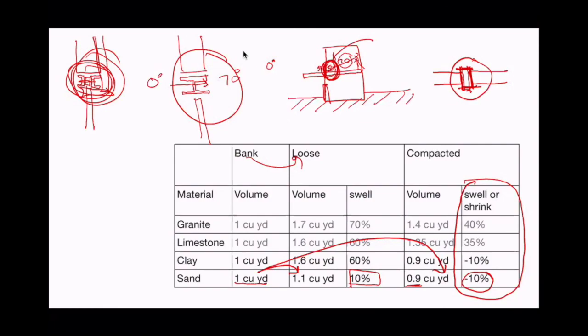it happens on your soda can in the summer, that's metal. It happens on your glass of lemonade in the summer, that's glass. So it's going to happen typically on metal and glass, and on metal and glass that's cold. Remember we said this was a 52 degree piece of steel just inside the building. If we have an indoor swimming pool in here at 70 degrees, and a 52 degree piece of steel, then yes, we will have condensation on that steel, and it does become a little bit about moisture.